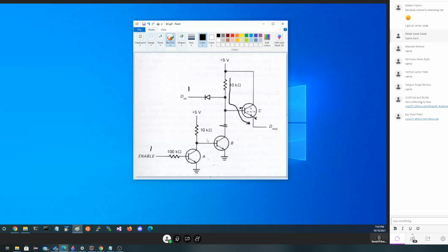So if the transistor's turned on, to get from here to here is basically the same thing. What's this guy hooked to? He's hooked to 5 volts. So that means the bottom of this is at 5 volts. It won't really be 5. It'll be a little bit lower, because the real drop here is probably bigger. But in just things, we know the transistor's on.